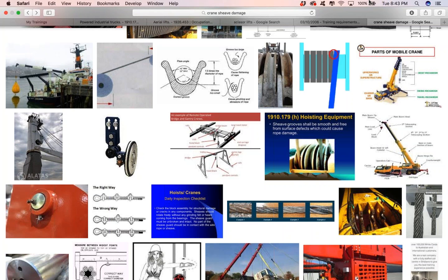We want to turn cautiously. We want to allow for extensions or attachments of the structures. Some equipment is top heavy. We need to respect that so we don't tip it over. Also watch the swing radius, folks, because the back side or the front side may swing out depending on the type of equipment. We have to know the turning radius and the swing radius of that equipment. We have to make sure that the swing path is clear of any people or any objects.